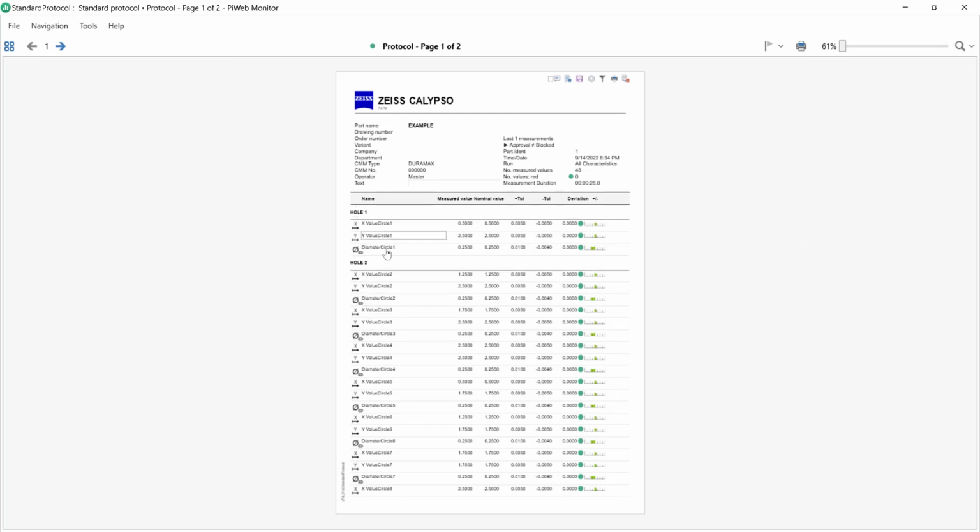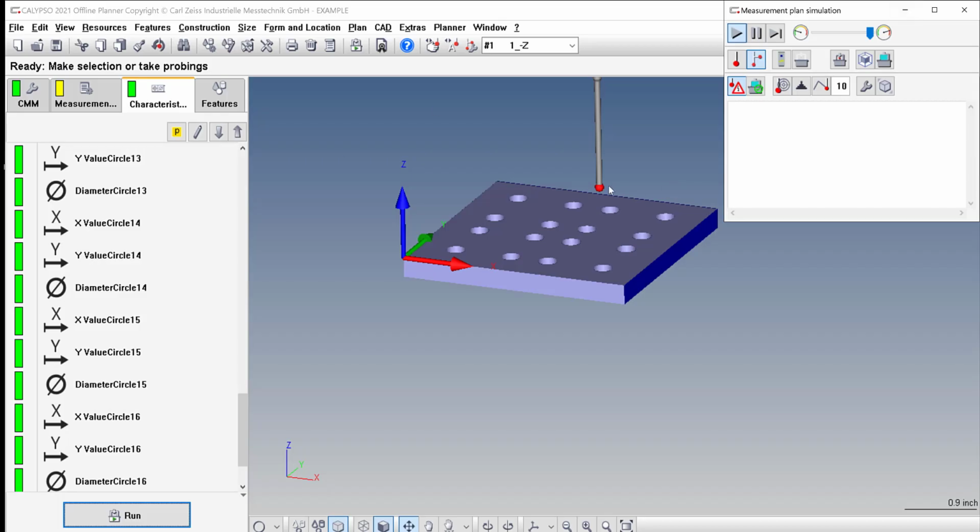It's a good idea if the stylus is close to the size of the hole or the tolerance is very large, that you always enter to the center of the hole to avoid hitting.